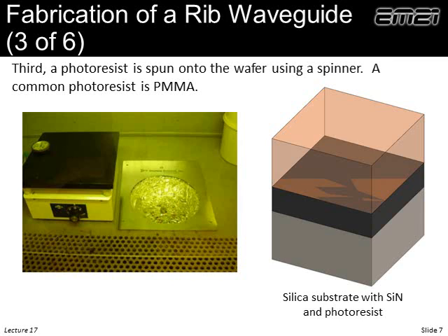Well, what we do now is we spin a layer of this photoresist. This is this goop that is sensitive to light. We would typically pour this on top of our wafer, just like it was pancake syrup, spin the wafer using some prescribed recipe, put it on a hot plate, bake it, and now it's ready to be exposed.